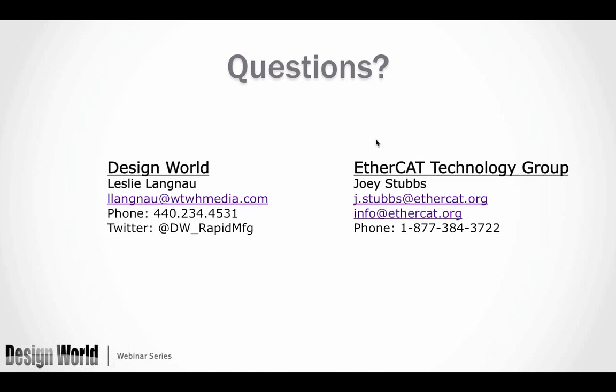Actually, that's a very good question. So the ring topology previously has been a little bit of a problem. You still use distributed clocks, but once your topology changes, then of course you have just changed the propagation delay throughout the network. So in the works right now are methods for having both a backup reference clock for the portion that's remaining if you have a break in the middle somewhere. But at any point you can still recalculate the individual propagation delays between the two halves that are left over and quickly resynchronize within a matter of fractions of a second.